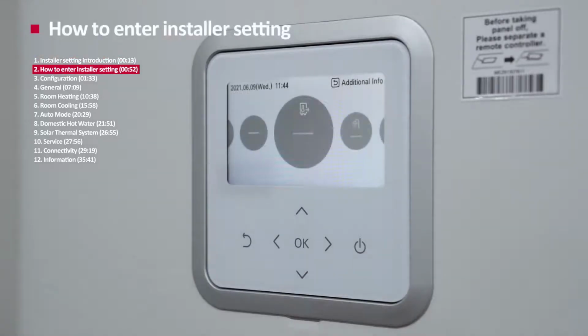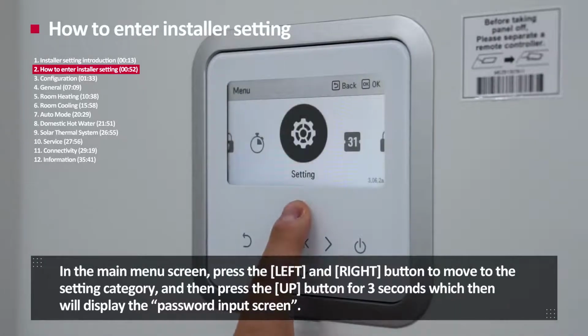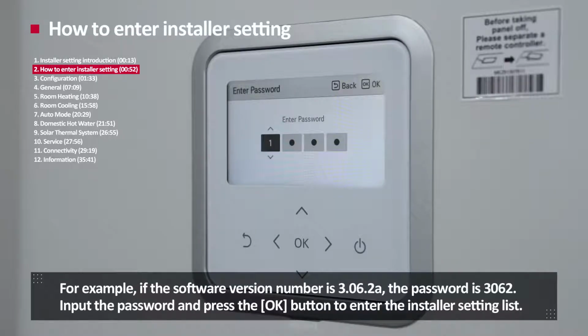How to enter installer setting. In the main menu screen, press the left and right button to move to the setting category, and then press the up button for 3 seconds, which then will display the password input screen. Initial password is the software version number of the remote controller, which can be found on the lower right-hand side of the screen. For example, if the software version number is 3.06.2a, the password is 3062. Input the password and press the OK button to enter the installer setting list.